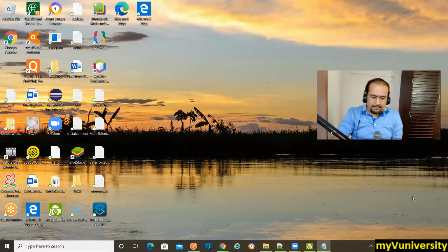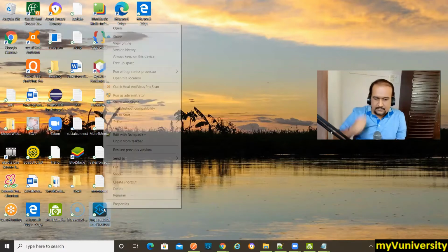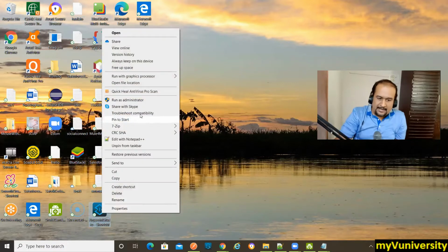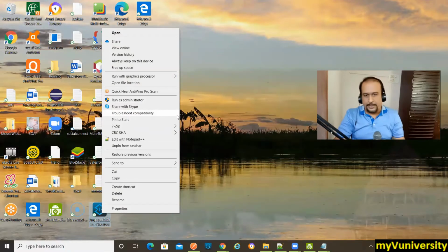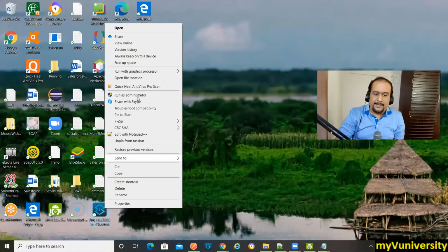Awesome. Okay, so now what we have to do is start Anypoint Studio. Sometimes there may be a problem with the admin rights of your user. Whatever user you logged in with might not have admin rights. So right click on this icon, and you can follow along with me. You don't have to just watch, do it. Right click on the icon and always go for run as administrator. Otherwise, if we just double click and start it, there may be a problem with the admin rights and it may not open. The better way is to always have the habit of right clicking and running as administrator.